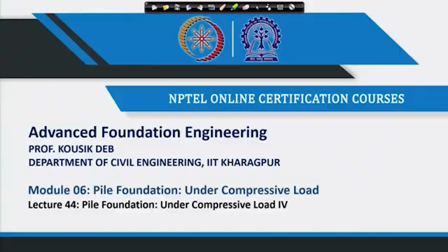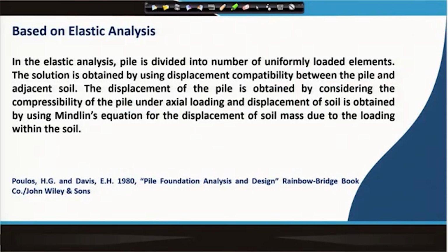Next, today I will discuss another approach, which is the elastic analysis. Based on elastic analysis also we can generate the load deformation curve theoretically. So, what is elastic analysis? In elastic analysis also the pile is divided into a number of uniformly loaded elements. The solution is obtained by using displacement compatibility between the pile and the adjacent soil. The displacement of the pile is obtained considering the compressibility of the pile under axial load, and the displacement of the soil is obtained by using the Mindlin equation for the displacement of a soil mass due to loading within the soil.